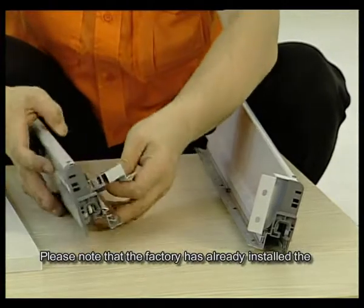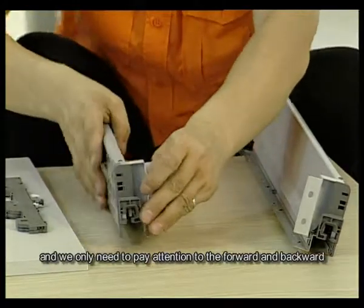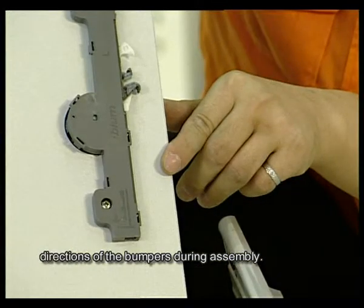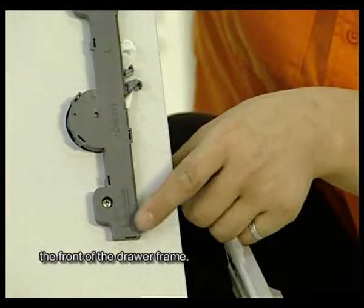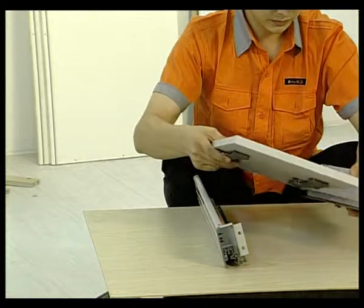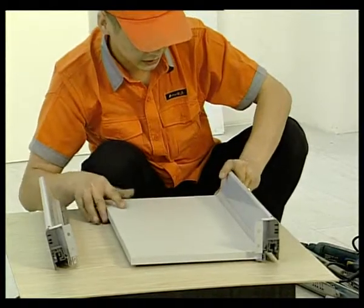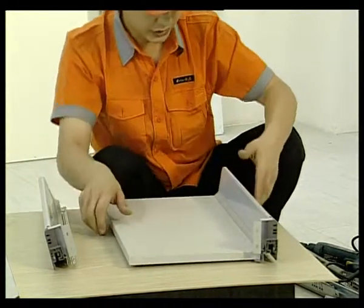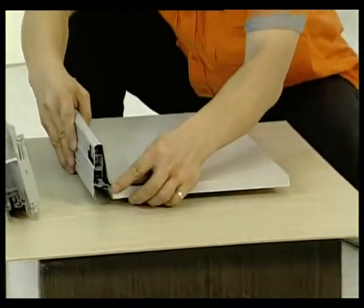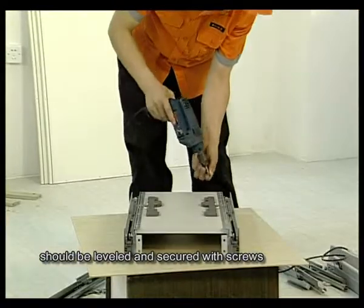Please note that the factory has already installed the soft close bumper on the bottom panels, and we only need to pay attention to the forward and backward directions of the bumpers during assembly. The arrows of the bumpers should face the front of the drawer frame. The front sides of the drawer frame and the bottom panels should be leveled and secured with screws.